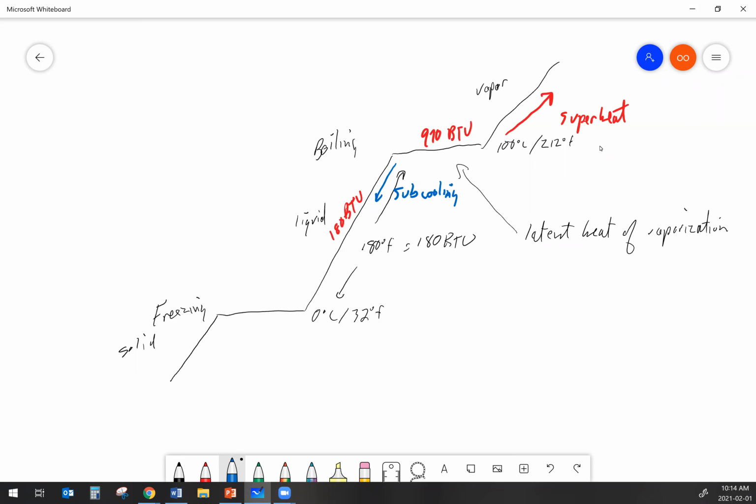In any refrigeration system, the critical thing is that we make it across the line, but we don't have excessive amounts of superheat, and we don't need excessive amounts of subcooling. If we stay right at that boiling point, we end up with the most heat transfer happening the most efficiently that we can.